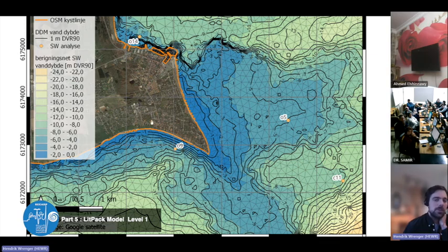On the other hand, if we go offshore too far, then these wave conditions are assumed to be changing along the profile only due to depth impacts, but not due to 2D impacts due to the wave diffraction around this headland.